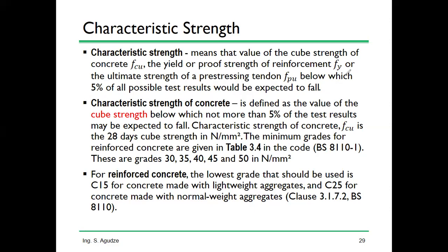You just have to know the size of the barrel, the wheelbarrow, because the standard wheelbarrow is actually 4 headpans. So you should be able to know how many headpans make up a full wheelbarrow that you are using on the site. And we know that two headpans make up a 50 kilogram bag of cement. So you should know how many headpans are within the wheelbarrow, and then you can also use that strategy to measure. But that kind of guesswork measurement on site must stop.